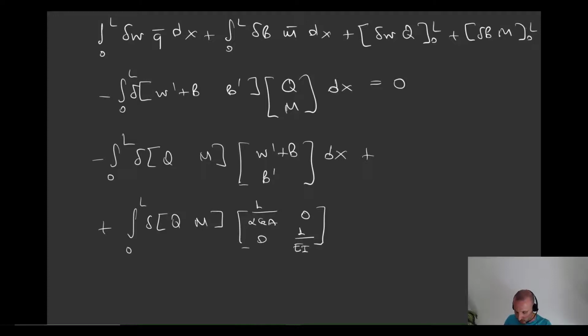And this is actually the matrix called the compliance matrix, which is actually the inverse of the material matrix, right? In this case, we have the compliance matrix. Okay, and this is going to be post-multiplied actually with the Lagrange multipliers themselves, actually the fields we seek for, dx, and this has to be equal to 0.